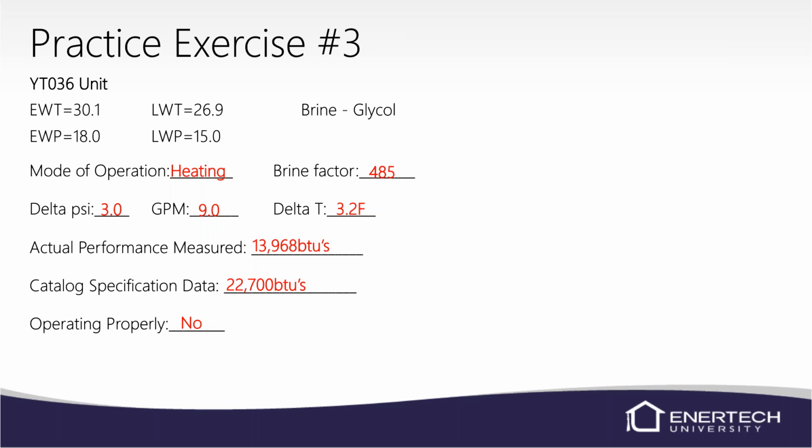In this, the first thing I would look at is, in first stage, the unit runs 2/3 capacity. And then in second stage, the unit picks up the other third of capacity. So the first thing I would look at is make sure the unit is in second stage. If the thermostat is calling for second stage, then I would look more towards making sure that the compressor is shifting into second stage, with amp draw or something like that. But this one kind of tells me it's stuck in first stage, or it could just be underperforming as well. Could be a refrigerant issue, but it's kind of funny how it's just off by that 1/3 of capacity.